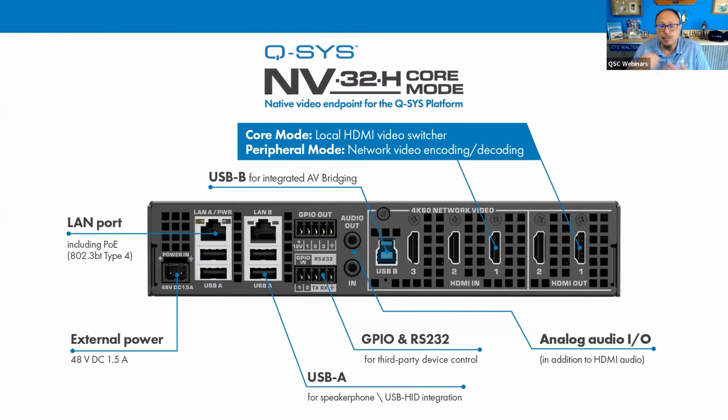Local power, we don't sell a local power supply, but if you choose to locally power it, you want to stay 48 volt DC, 1.5 to 2 amps is good there.